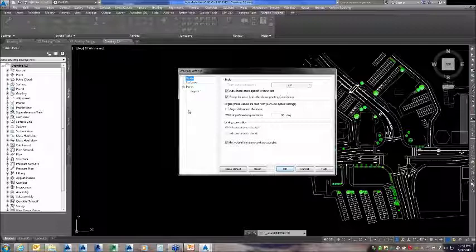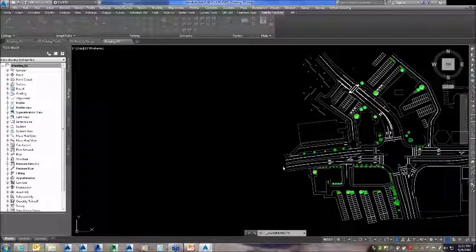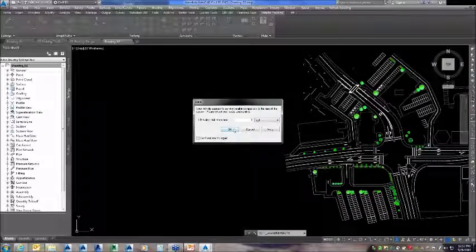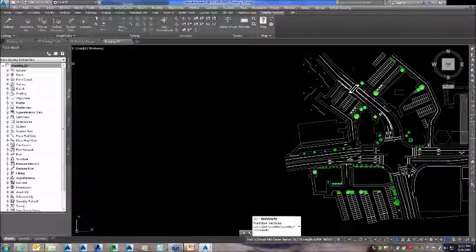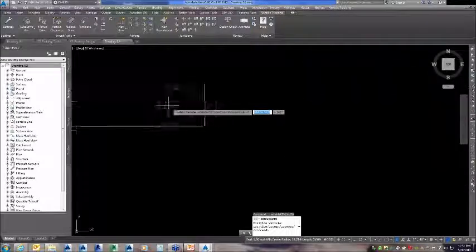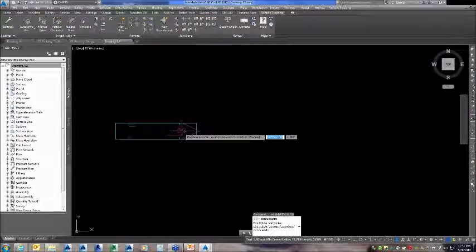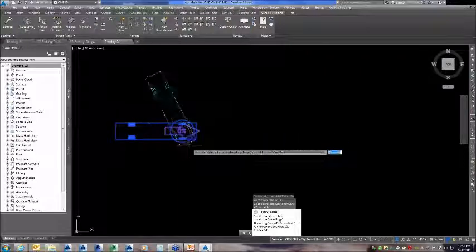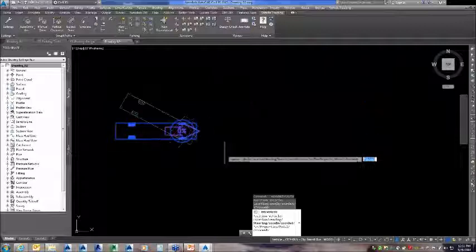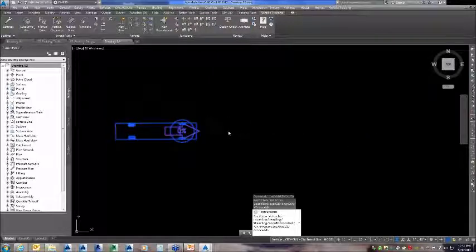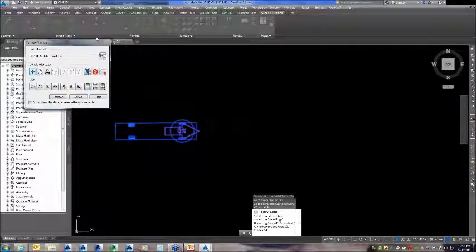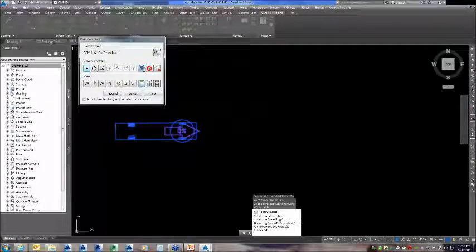Now, when I draw out the specific path, it goes on specific layers. And then it's prompting me for auto check against scale, my window size, and those type of things, driving convention, and then angles. And if I select OK, then it brings up just a quick reference to my scale, always drawing things 1:1, and then it puts a little vehicle here. So if I pick on it, I have the ability to change the direction of my vehicle, and if I just pick it right there, it's going to give me a second chance in reference to the vehicle that I'm using.